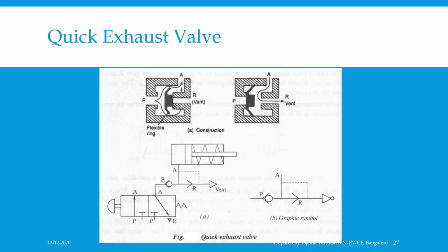When P is connected to high pressure, the shuttle blocks the port R, connecting the ports P and A. High pressure air extends the cylinder. When the direction control valve is deactivated, the port P is blocked by the shuttle and exhaust air flows to R through A. Fast exhaust valves are usually mounted directly onto cylinders and speed up response by avoiding any delay from the return pipes and control valves. This can also be used as a simple control valve.